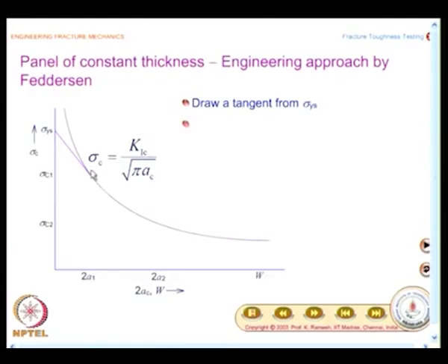I am not going to get into the details, I am going to give you the final values. So, that means the residual strength diagram will have a straight line portion plus a curve, and you know this goes beyond the panel width. Suppose my panel width is this much, what is the useful range of my residual strength diagram?